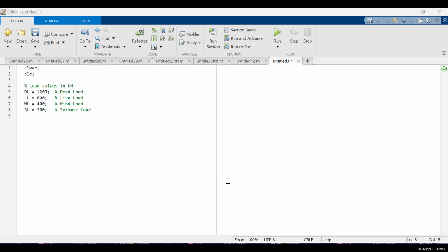So load combination is when you combine different loads on a structure in order to see how the structure will perform under different conditions, right? Those loads can be the self weight of the structure. It can also be the live loads, just the load from people, the loads from furniture, the load that can move, can vary.